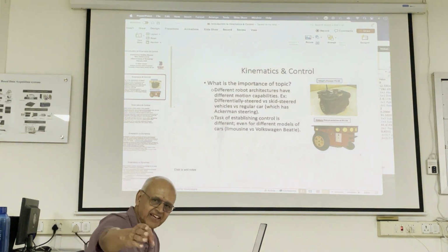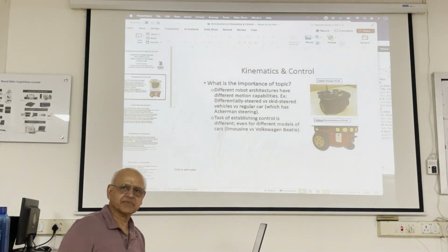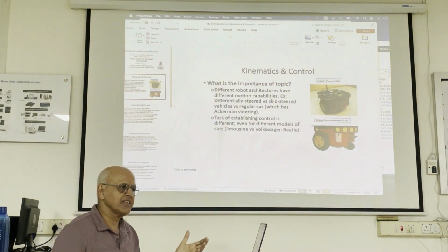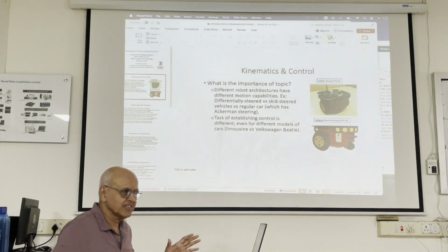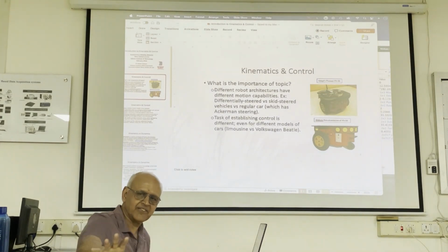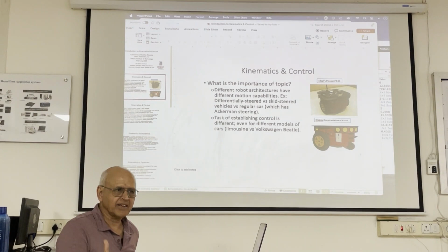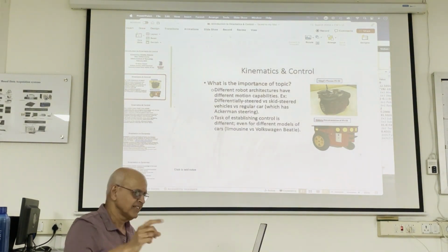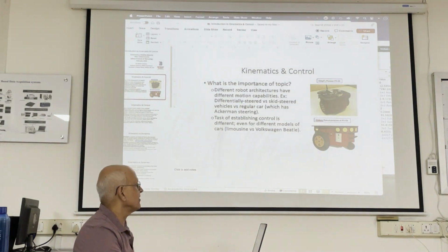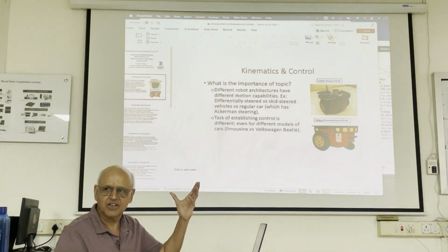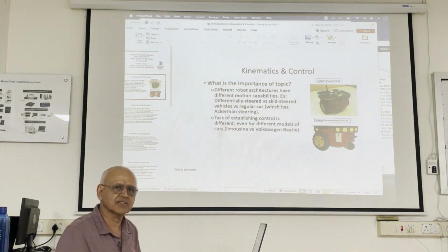So you see there, it has two caster wheels in the front. You can have one caster wheel, right? But if you have two caster wheels, there's more symmetry and support, because then the weight can be distributed. It has two nice motors. It doesn't have any controller or anything like that right now, but it can be built up again. So that had a joystick to control it. This one you can have a joystick to control too, but it's meant to be autonomous, and so a computer program gives it the instructions to drive.